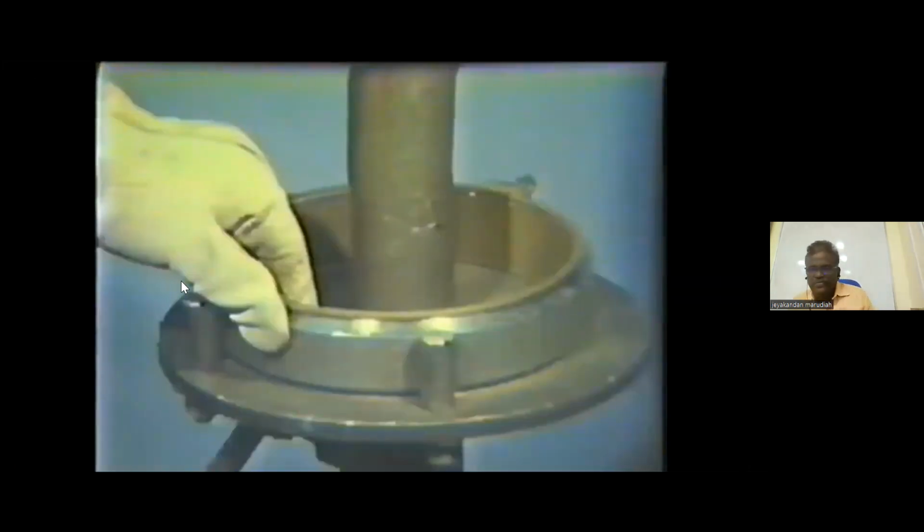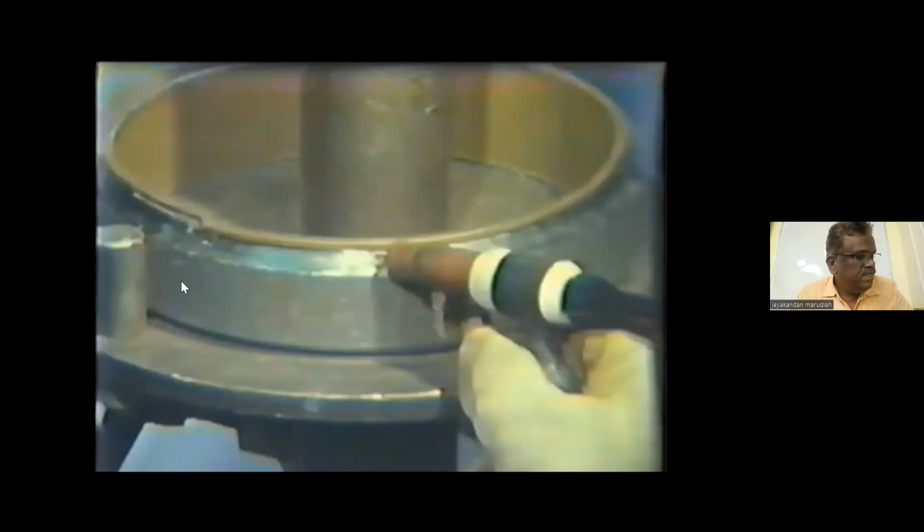Place the insert at the end of one of the freshly prepared pipe joints. Note that the insert is slightly larger than the pipe, which will produce some overlap. Fit up should be as accurate as possible. Make a small tack weld within 2 inches of the ends of the insert. This tack weld is made without filler metal and joins the insert to the joint bevel.